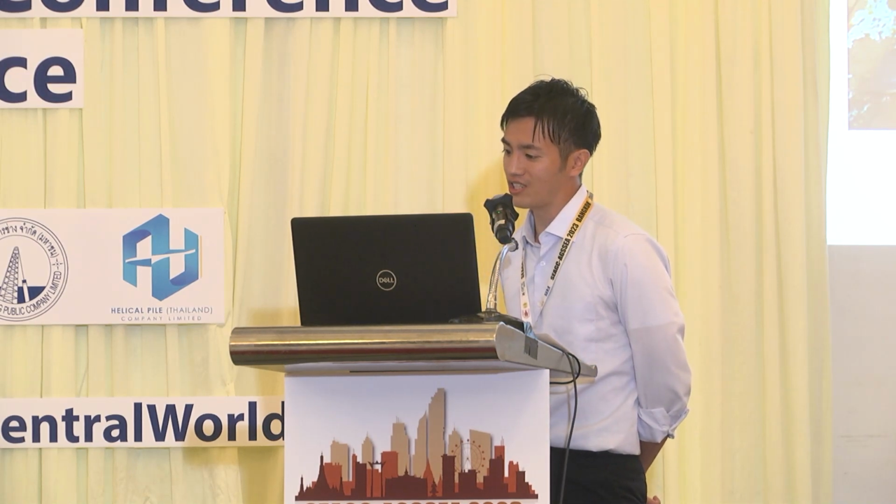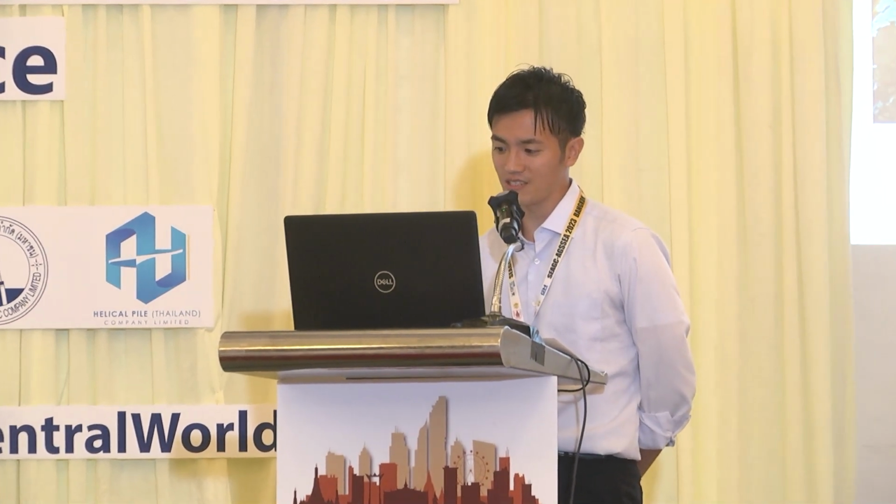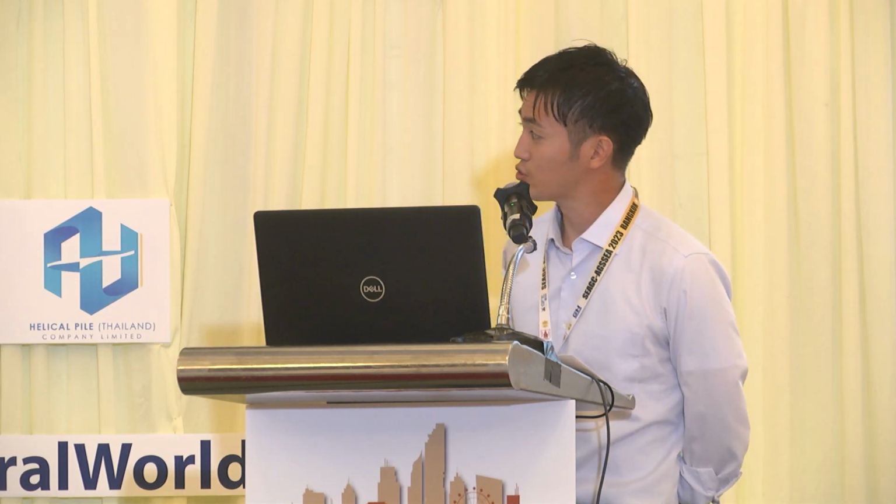In this study, the role of this unique structure was interpreted from a geotechnical engineering perspective. Based on the role of the mound in protecting the mound and the stone chamber, two hypotheses were formulated in terms of strength and drainage properties, and geotechnical experiments, a triaxial compression test and a rain penetration test by sandbox, were conducted. First, I am going to explain the triaxial test.